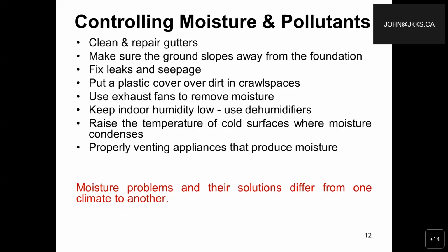Use exhaust fans to remove moisture, and certainly the old standby, even prior to things like heat recovery ventilators, is simply an exhaust fan to remove moisture. Isn't that what we should be doing in any bathroom, or perhaps even any kitchen, or actually in any moisture generating area, including potentially even the laundry room? We want to keep indoor humidity low. We want to use dehumidifiers.